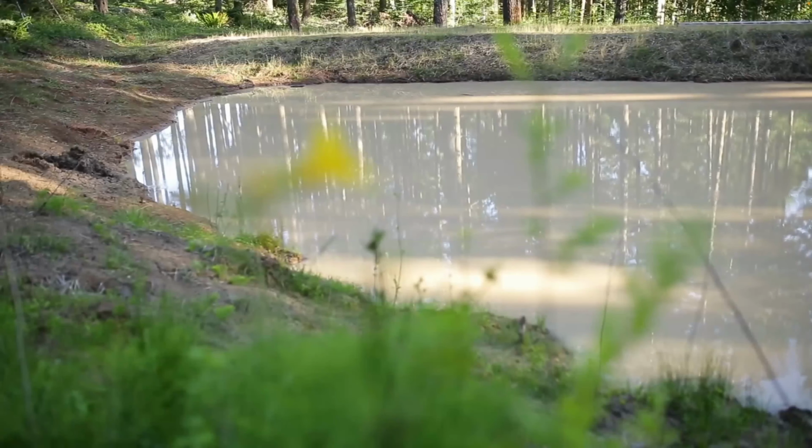It's also important not to have large trees in a location where, if they were to be thrown over and uproot, they could break your dam substantially. Your spillway also every year should be evaluated and cleared if there's any accumulated sediment or certainly brush material in it.